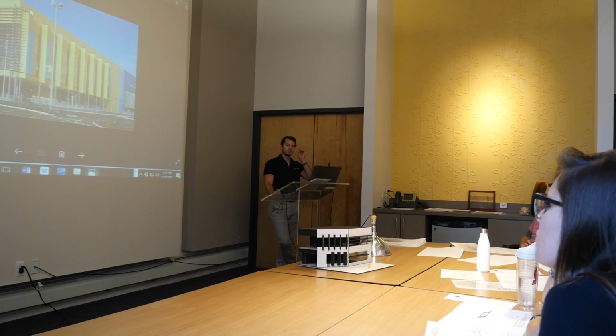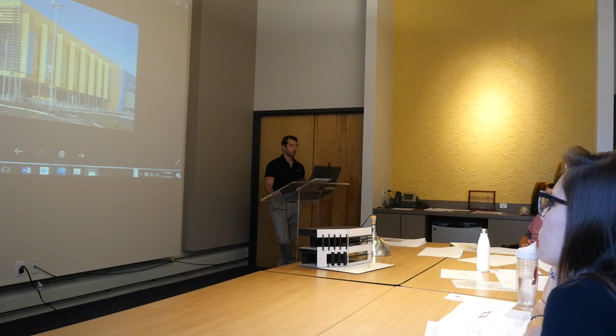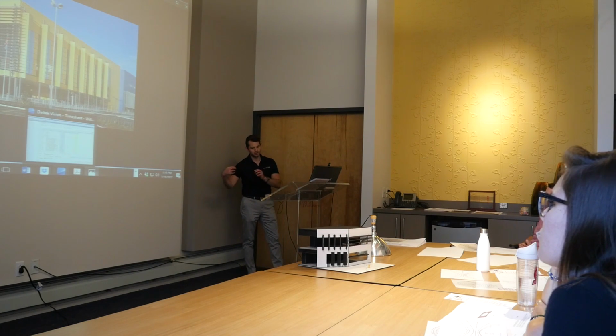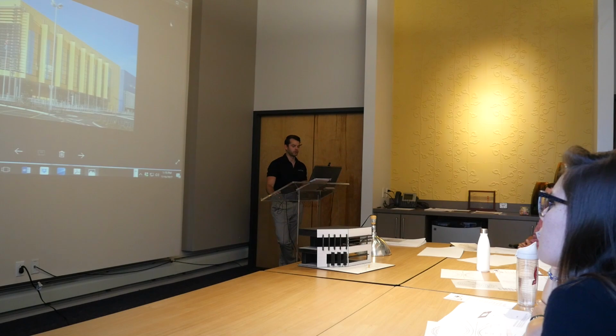One thing I don't think I touched on, but you can see it on the model there, is south facing because of the sun path, how we saw on the solar chart. When you see louvers that are horizontally oriented, you're generally looking at the south face of the building. The sun is high, it's usually facing that building pretty directly. On the east and west sides, you generally see vertical louvers because the sun is much sharper in the sky and it's coming into your building at odd angles. It's much more difficult to control.